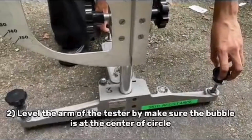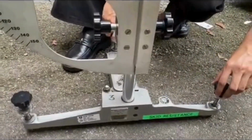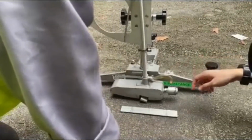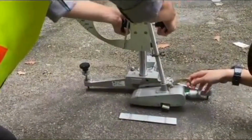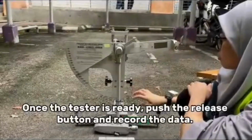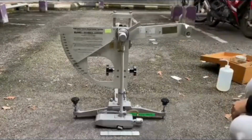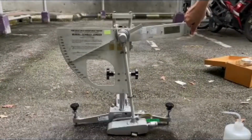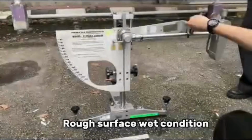Level the arm of the tester by making sure the bubble is at the center of the circle. Next, adjust the level by making sure the slide rubber touches 3 points. Once the tester is ready, push the release button and record the data. Run the experiment at smooth surface at dry condition for 3 times. And then repeat the same procedure at rough surface for 3 times.